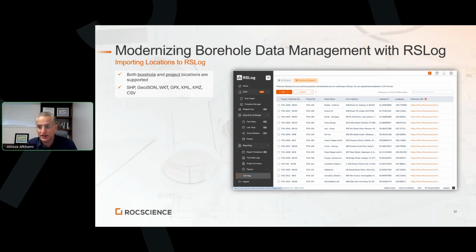In this screenshot, you see that we imported 2000 historical data points as CSV. Under New, if you click this arrow button, you can import from CSV. The only thing you need is a title for that data point.